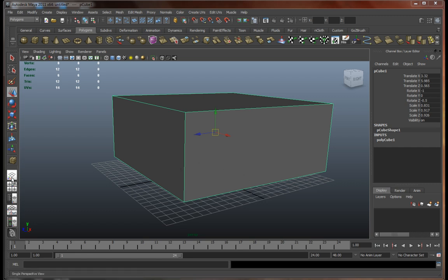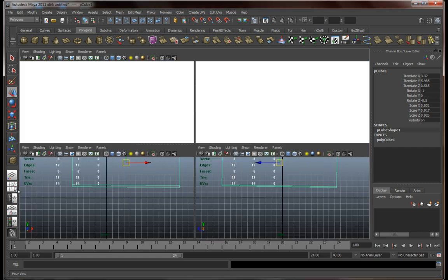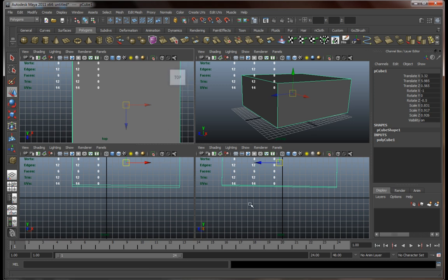Alright, now that we finished with these guys, let's check out what we have further down the road. The first two help us with our viewport. These guys over here. How's that, you're wondering? Well, it's pretty simple. The first one is our perspective view. The second one splits our viewport into 4 panes, 4 views, alright? 3 of them being the direct top, side, and front view, and the fourth being our initial perspective view. This really helps out when creating something a little more complex, especially when you're working with references.